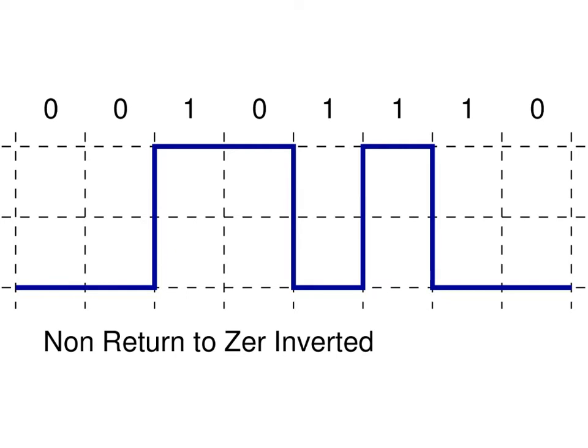So if each pulse is 2 milliseconds, then in 1 second we can have 500 pulses. Okay. Now, a more general term, instead of calling it a pulse, when we deal with any signal, we'll talk about also a signal element. Signal element.